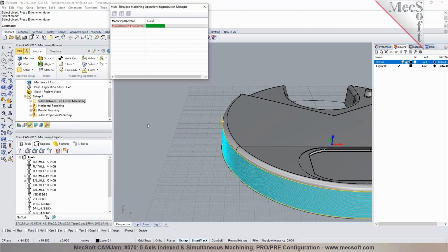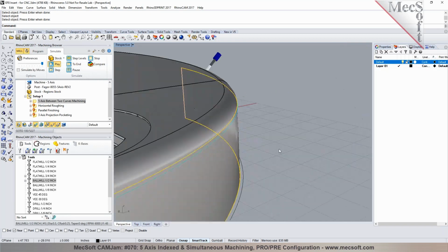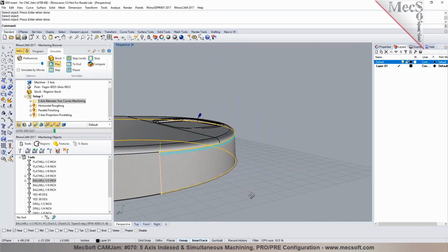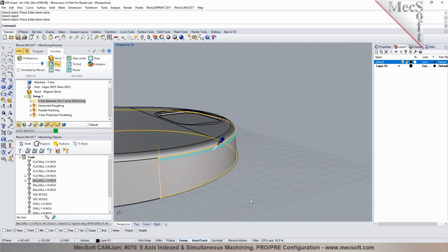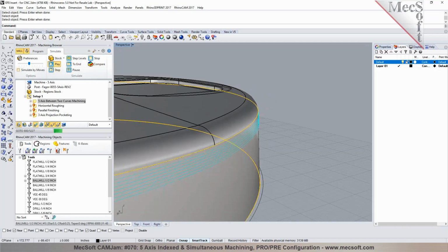So you can basically tilt the tool to a certain angle to cut it, depending on how you want it to be processed. So now you can see that the tool is set at 45 degrees. Do you see the difference between the lead lag angle versus the tilt angle, sir? Perfect. Are you seeing it in the tilt? Yep, works good.